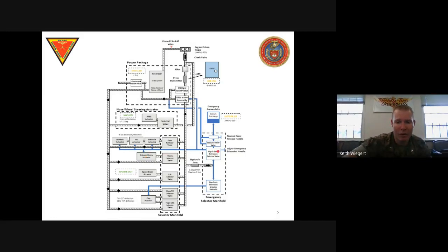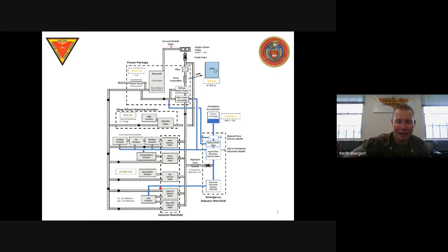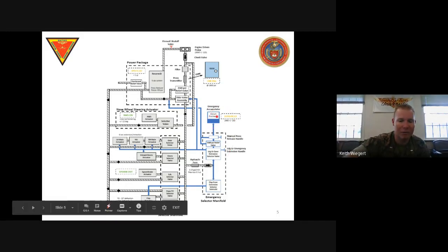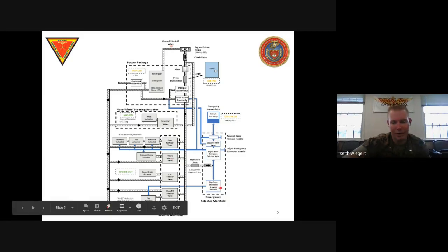Cool. Any pressure that's left over is going to come down here to the flap emergency extension selector solenoid, right? So you're going to have your flaps available to you, and that's going to send it over to the flap actuator. You can either put them at takeoff or landing, or you can go takeoff and then landing. But remember, if you go landing, you can't come back up to takeoff, right? It's a one-time use kind of thing because we're just using what pressure is left over here, right? Most of that pressure is going to go to put your gear down. If there is not enough pressure left for your flaps, tough luck. You can do a no-flap landing, right? The best way you can check that is you've got your E-hyd pressure low, right?